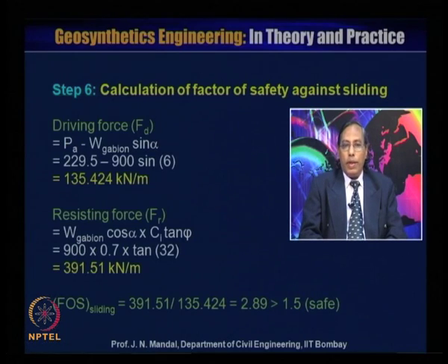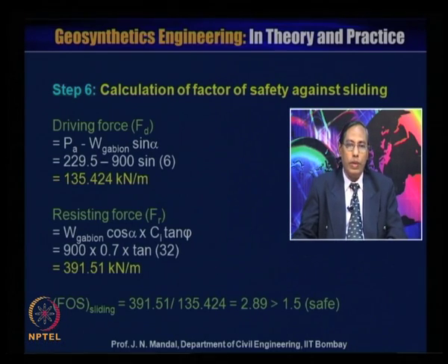So, factor of safety against the sliding will be equal to resisting force Fr divided by driving force Fd. So, this will give 391.51 divided by 135.424, this is 2.89, and that is greater than 1.5. So, it is safe.